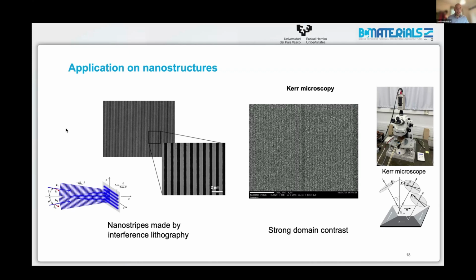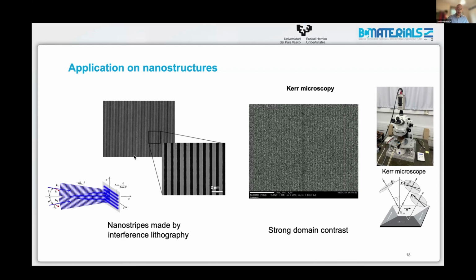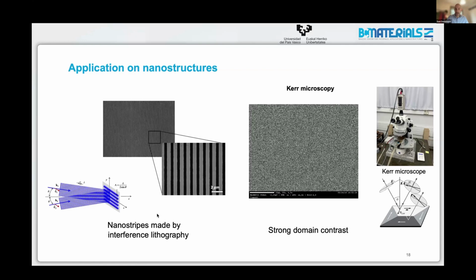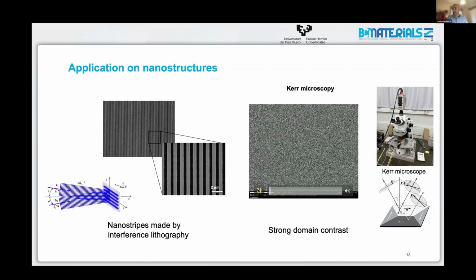If we use magnetron sputtering, we can have a precise control of the thickness and also the degree of diffusion between layers. But the problem is, since we are interested in getting into nanostructures, we prefer electron beam evaporation due to its deposition geometry. But if we want to work with thin films, maybe we should work with magnetron sputtering.